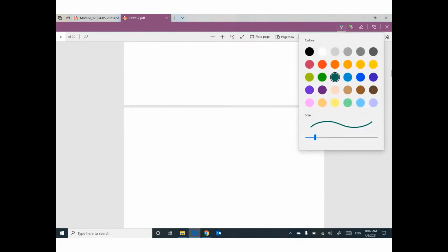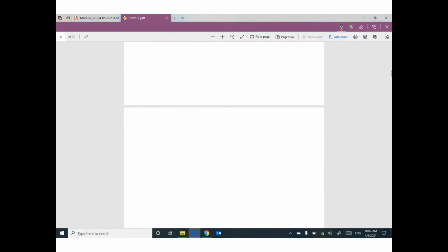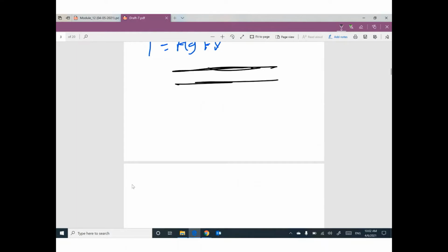Guys, we don't recommend this cross section. Your thickness of the concrete slab is small, so the neutral axis will be within the steel beam. We don't like this. Do you know why?